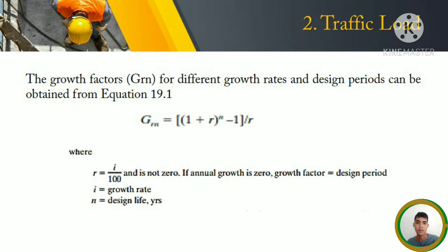Since traffic volume does not remain constant over the design period of the pavement, it is essential that the rate of growth be determined and applied when calculating the total ESAL. The annual growth rates can be obtained from regional planning agencies or from state highway departments. These usually are based on traffic volume counts over several years. It also is advisable to determine annual growth rates separately for trucks and passenger vehicles, since these may be significantly different in some cases.